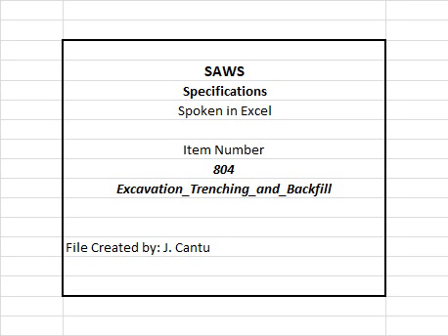804.5 Construction. All existing utilities shall be protected from damage during the excavation and backfilling of trenches and, if damaged, shall be replaced by the contractor at their own expense. 1. General. A. Unless otherwise shown in the contract documents, all excavation shall be unclassified and shall include all materials encountered regardless of their nature or the manner in which they are removed, to include but not limited to groundwater, water, rock, stone, sand, concrete, organic material, existing abandoned utility lines whether shown on the plans or not, or any kind of material that is encountered.